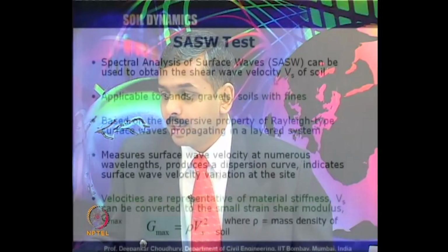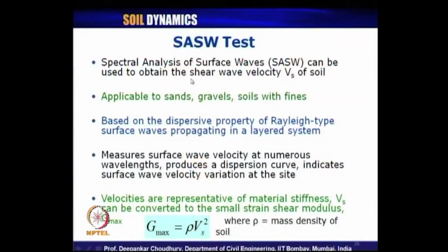How? We know the relationship between Rayleigh wave and shear wave, depending on the Poisson's ratio of the material, so we can compute the shear wave velocity of the material. That expression is used to obtain the shear wave velocity. So we first use the Rayleigh surface wave, through which we finally get the value of shear wave velocity.